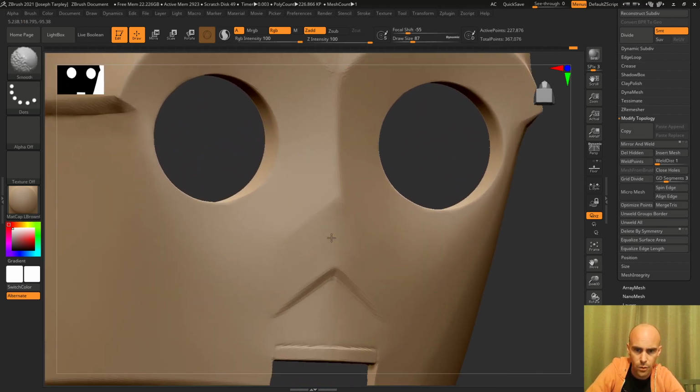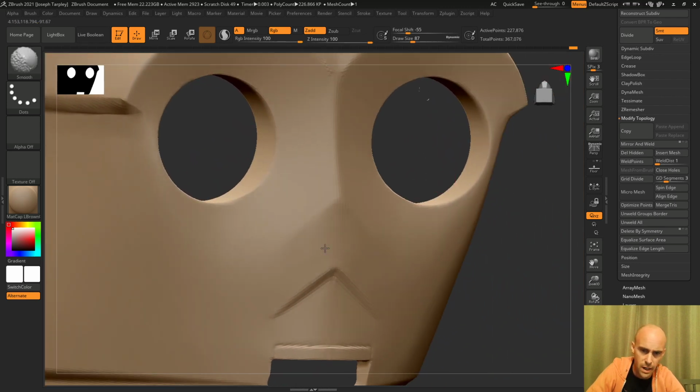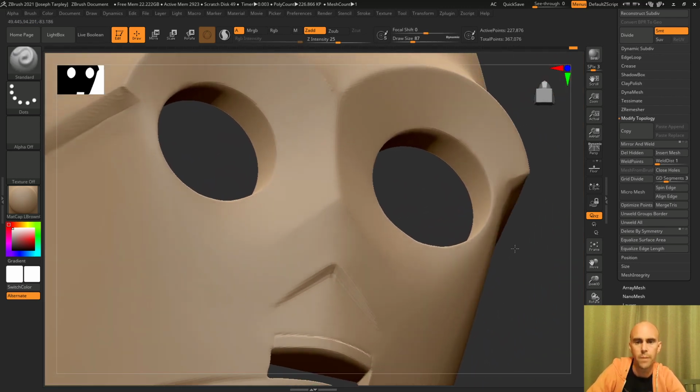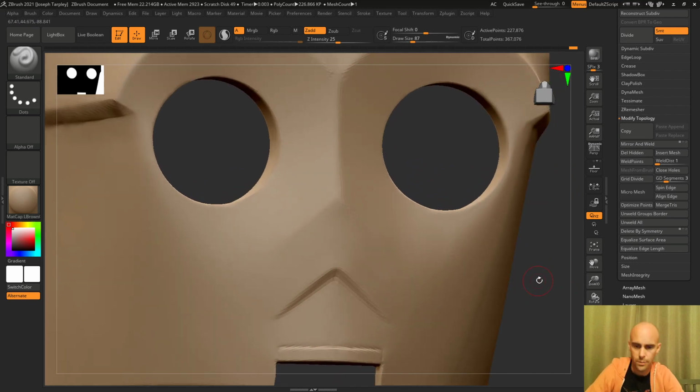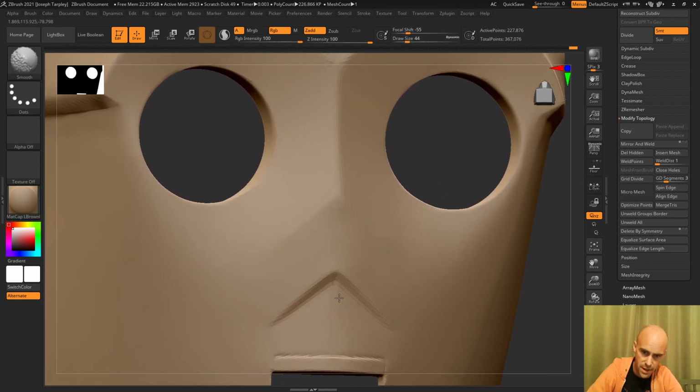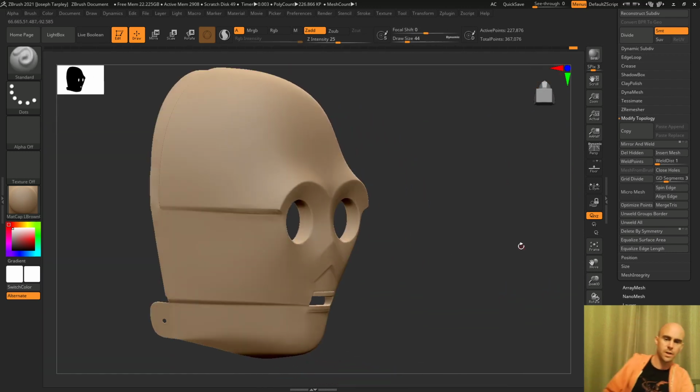But typically in a lot of poly modeling 3D programs, you work at a pretty low resolution and then use a modifier. In Maya, there's a smoothing option, and in 3D Studio Max, it's called Turbo Smooth, and you can work at a low resolution with big chunky polygons. And when you turn on Turbo Smooth, it'll tessellate the geometry and basically turn up the geometry and interpolate the curve that would be made.